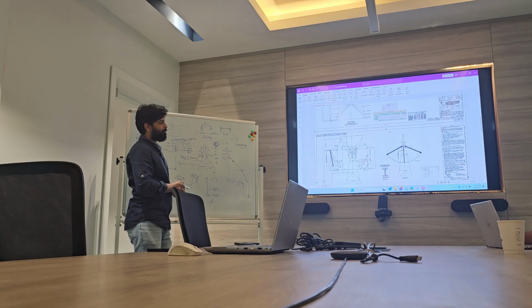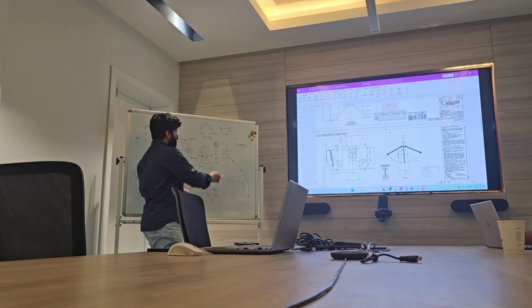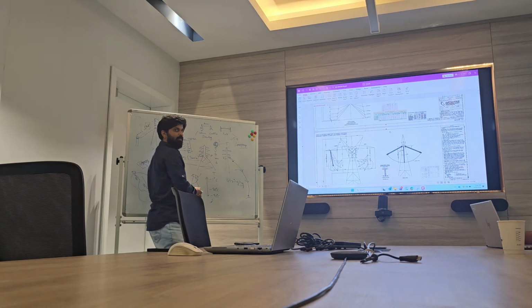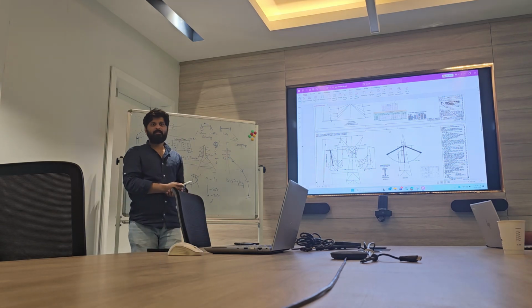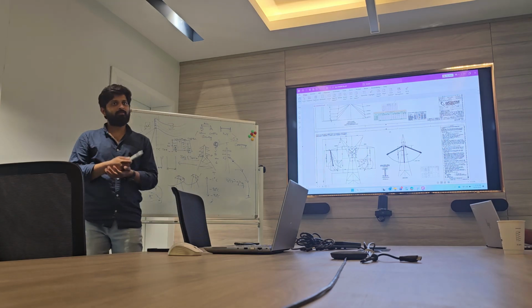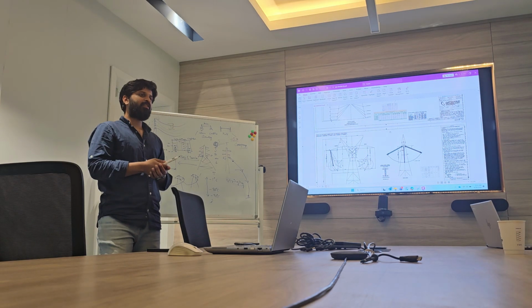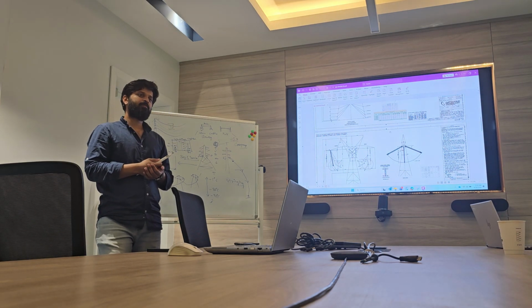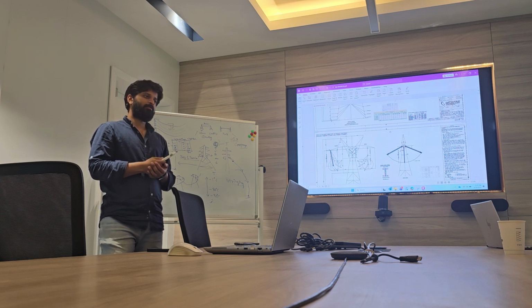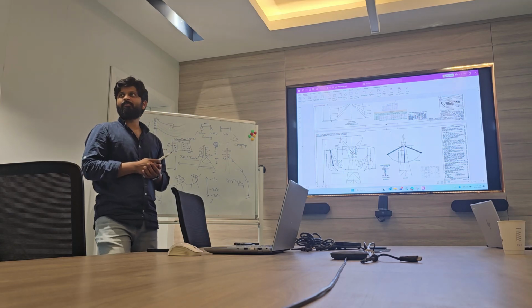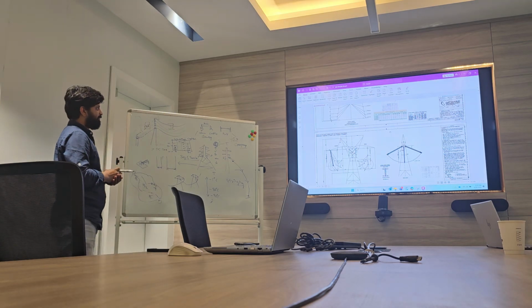Now, when we make tower design and when we make stringing, will we use the full strength of the conductor to pull? Will we use full strength of the conductor to design the tower? Why? Because of safety. Okay. How much safety will we keep? I mean, you keep a normal safety margin.